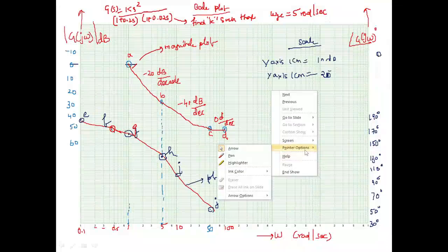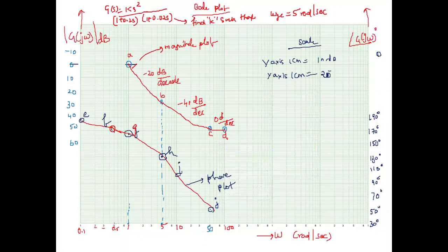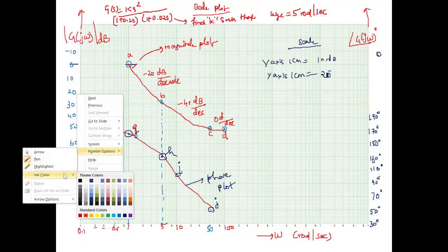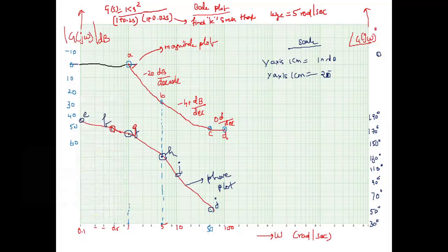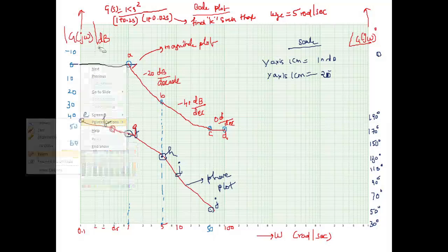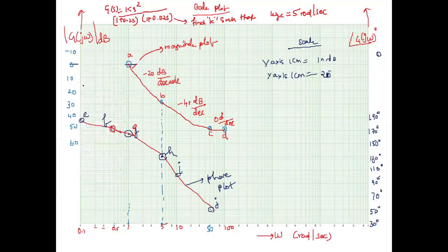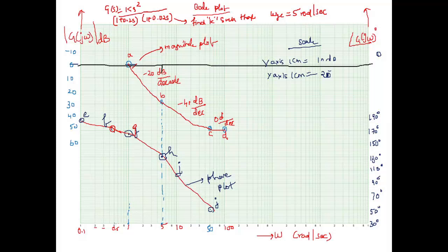Up to this, the Bode plot is over, but our problem is to find the value of k such that the gain crossover frequency is 5 radians per second. What will we do? This is very simple. Take a scale and put a horizontal line over 0 dB. After that, take 5 radians per second and put a line there. This is my gain crossover frequency. Now, at the gain crossover frequency...